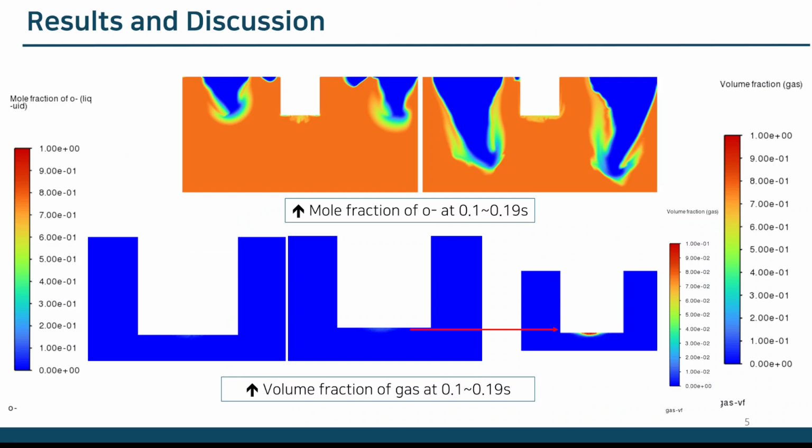It's being calculated until it reaches a particular time, which is 0.19 seconds, and then it does not converge anymore. Does not seem like a problem that might be resolved by simply moderating the time step size, even though it is a continuity convergence problem. And why I see like that is because it still hardly converges when the consumption and nucleation source terms are allotted in this whole fluid cell zone. Therefore, it is reasonable to presume that multi-phase flow model of mine has a stiff convergence condition.